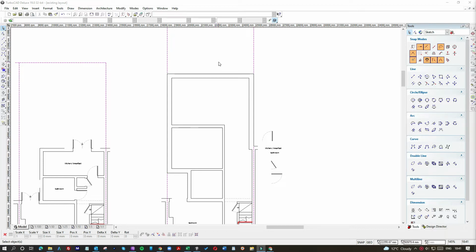And what we want to do is minimize the return on either side of the back wall here. I say minimize, we could actually do full width, but then there are going to be structural issues, which will raise the costs. If we can do 600 or 650 inside, that will reduce the structural costs, because it means we probably won't require underpinning in this section.